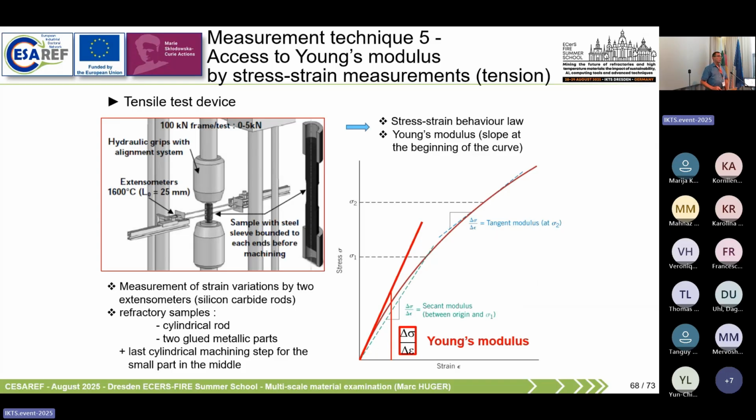If you do measurement with a mechanical test, you have no choice because of the sensitivity of the equipment. You require a high level of strain, because if you would like to measure something, you need to go above the resolution of your system. In that case, you have a lot of chance to engage defects inside your system, and then you measure things which are different in comparison to the other technique.